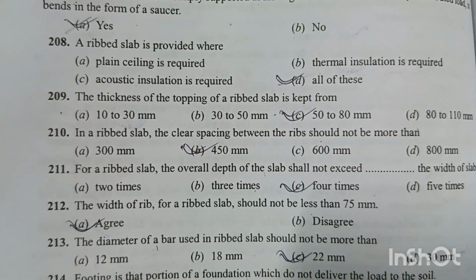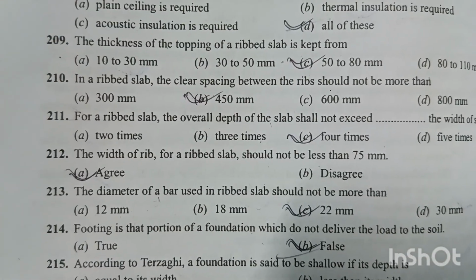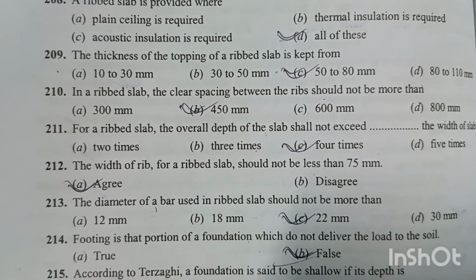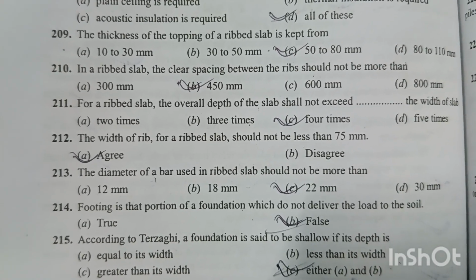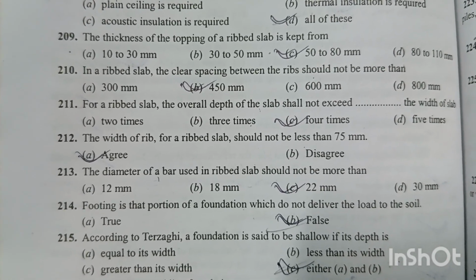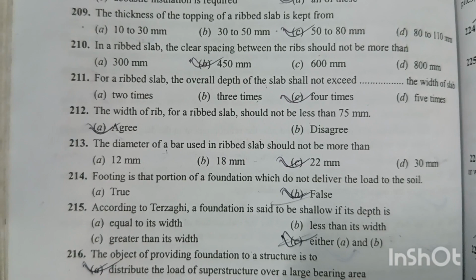Question number 213. The diameter of a bar used in the ribbed slab should not be more than 22 mm. Option C is right answer. Question number 214. The footing is that portion of a foundation which does not deliver the load to the soil. No. Option B is right answer. False. Question number 215. According to Terzaghi, a foundation is said to be shallow if its depth is equal to its width. Option A, equal to its width. Option B, less than its width. Option A and B. That means option C is right answer, either A or B.